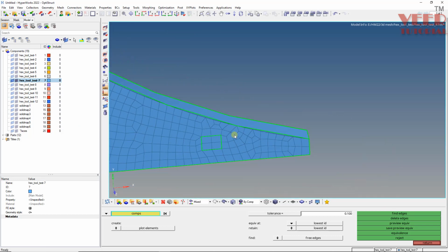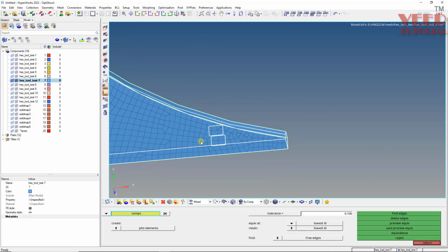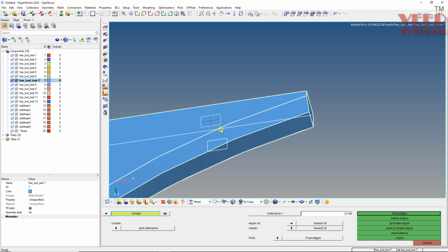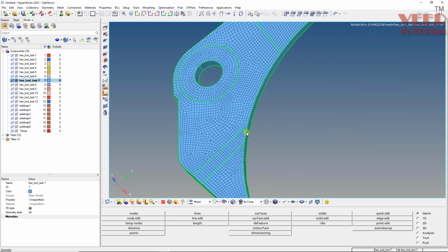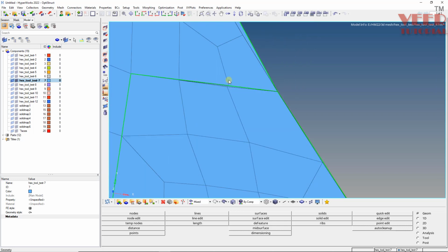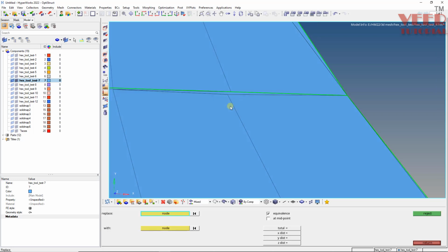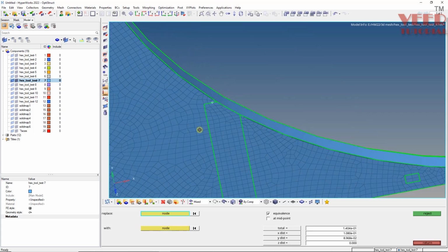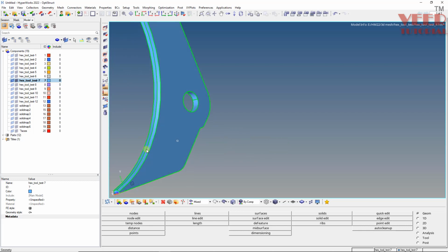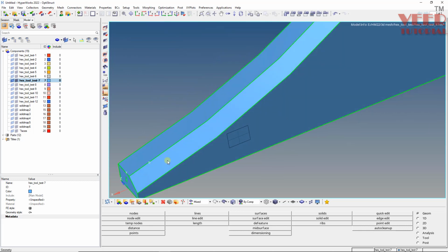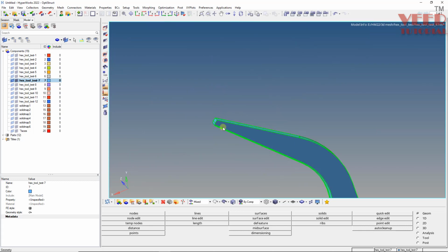So first let's check why it is showing free edge here. Preview cleanse. Okay, this edge, this was for this. Okay, no problem. And we have to equivalence them. So F3, pick up this and this. Then this will equivalence. After this we can drag this from left to right. So here CAD is looking fine here.